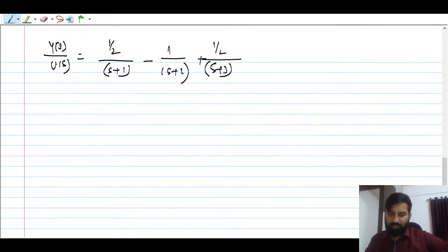Now you take this U this side, you multiply with the numerator here. So Y is going to be equal to, you can forget about the s variable now. You have to implicitly assume that there is an s, your output is a function of s, but forget about s now, because now I'm going to write everything in terms of state variables.